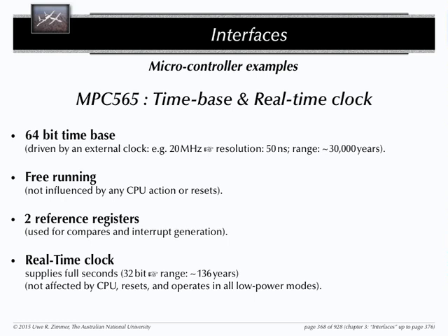Ada gives you both of these times. You have the calendar time, that's real time. Calendar time, as the name suggests, has something to do with the sun. And calendar time doesn't give you any guarantee in terms of whether it's corrected forward or backwards. And you have monotonic time. Monotonic time can also be related to what has happened outside, but it only ever goes forward, which makes your real-time designs a lot easier. Because we defined real-time clocks and free-running clocks, which are exactly defining these kind of things in hardware for you on your devices.